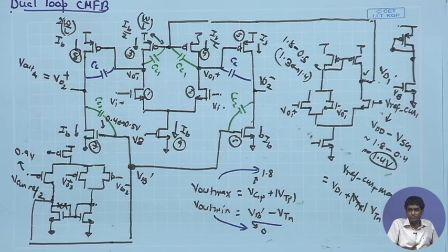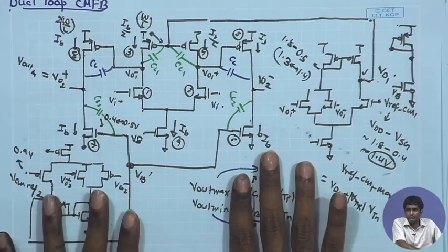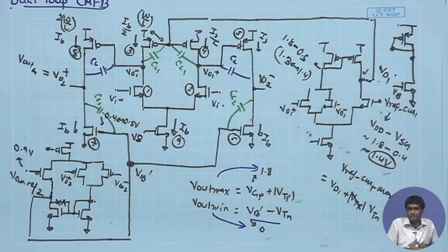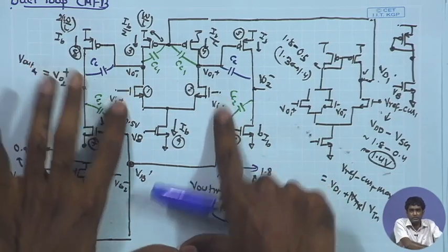Likewise, when you are doing differential simulation and trying to assess the stability of differential operation, you would like to keep the two common mode feedback loops intact, so that they are taking care of the DC biases of the output node. And input node, we had some special consideration that we discussed that day.